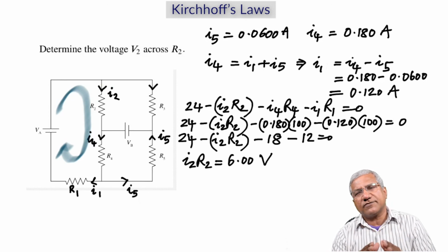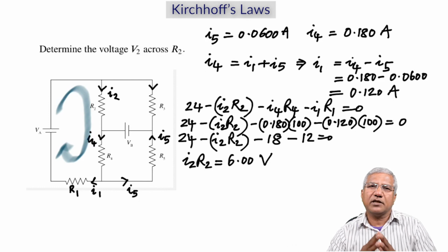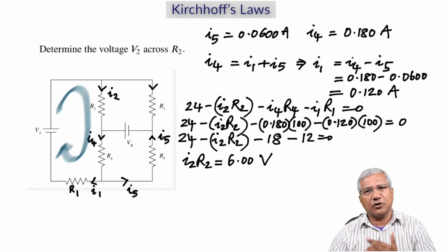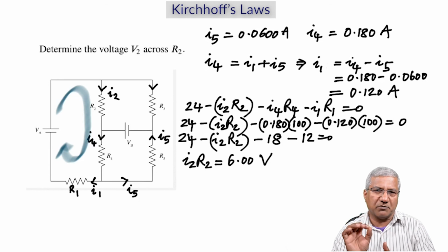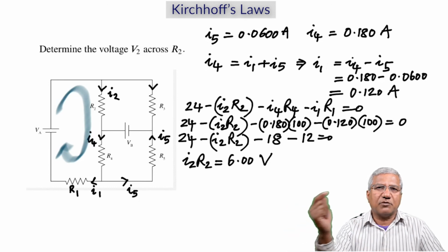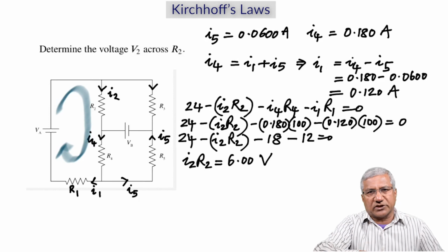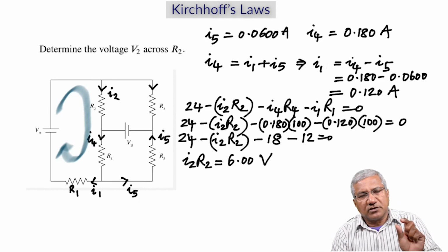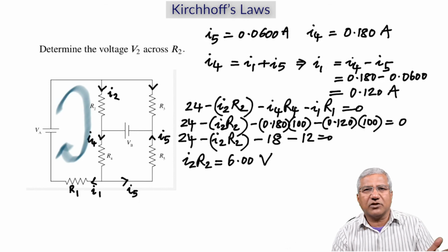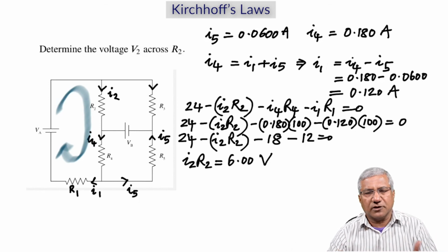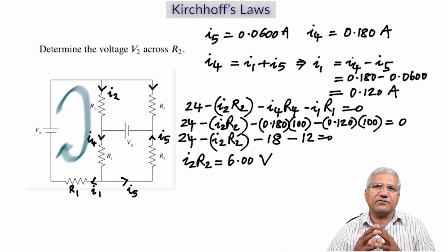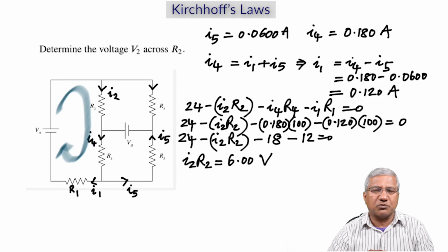So this video simply shows you how to apply Kirchhoff's junction rule and the loop rule. So the important thing is to remember that when you go from the negative to the positive of a battery, it's plus the voltage of the battery. And then when you go in the direction of current through a resistor, it's negative current times that resistance. That's all you got to know. And then the math comes in. So I hope this video gives you more insight into solving such circuit problems, because we will have these on the exam.